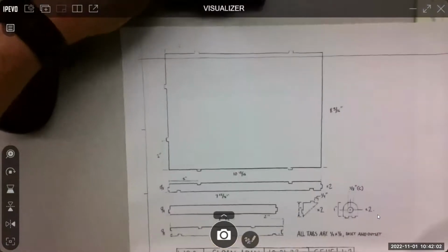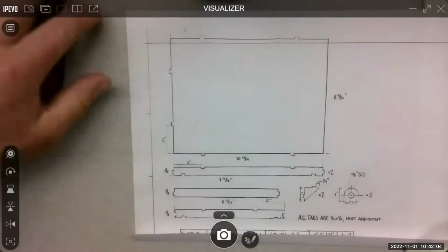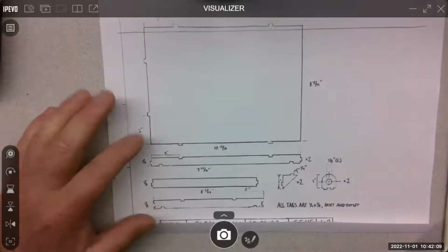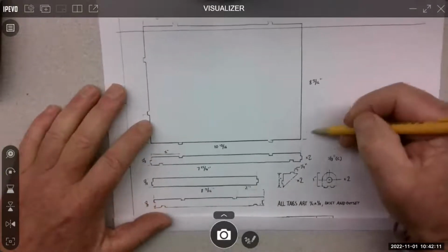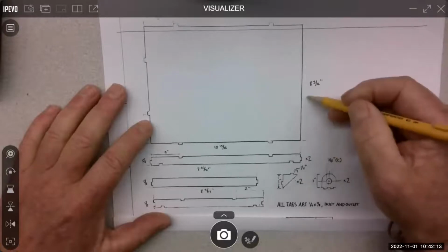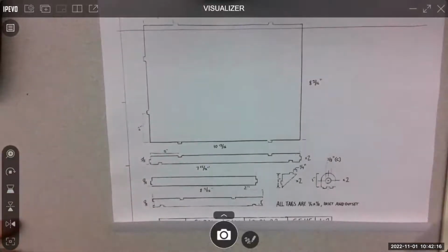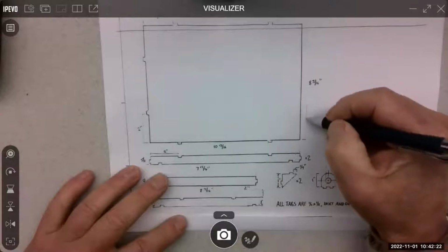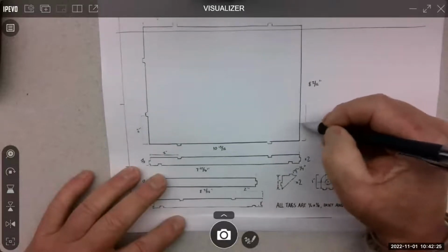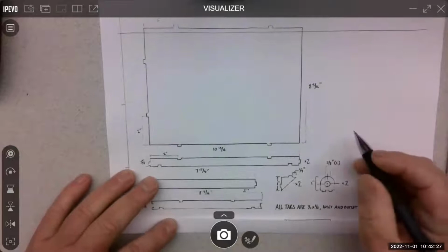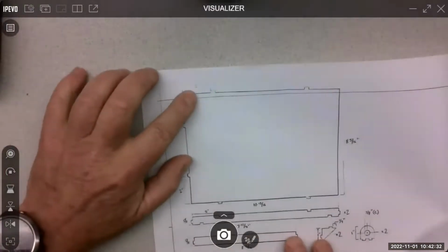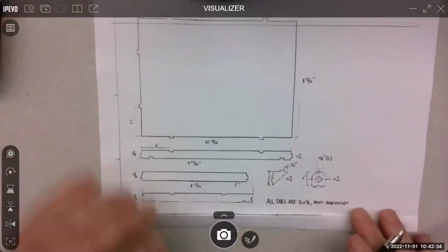So this is okay. When I printed it, the dimension lines didn't show up that great. So you have to get things black, right? There is a dimension line here, but it's just not showing up when you go to print it or make a copy. So make sure everything's dark. This student probably tried to make these really thin, because they're supposed to be thick and thin. That's good. But make sure it's just black enough to reproduce. That's helpful because there's a few dimensions that just didn't show up perfectly.